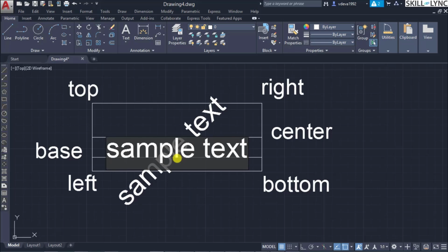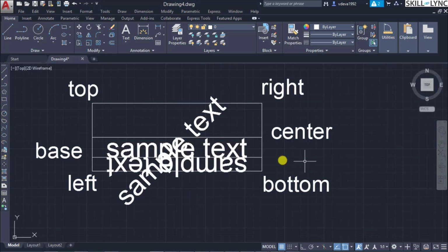So this is to ensure that your initial alignment is okay, that is the angle is 180, but for ease of typing AutoCAD shows it in the same format, but you click on outside and then click on escape to have it affected. So now you can see that the text has been rotated 180 degrees, that is the text has been specified upside down. So this is how your command is going to operate.